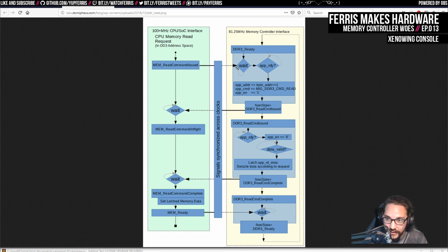Each one of these would have a synchronizer chain here, here, here, and here. He's essentially doing this really high latency closed loop solution that should be really safe, but he's going to have synchronizers on all those. But what was interesting is he only did synchronizers on these control paths. On the actual data that gets latched that he's sending either way, he didn't do any synchronizers. And that apparently worked.